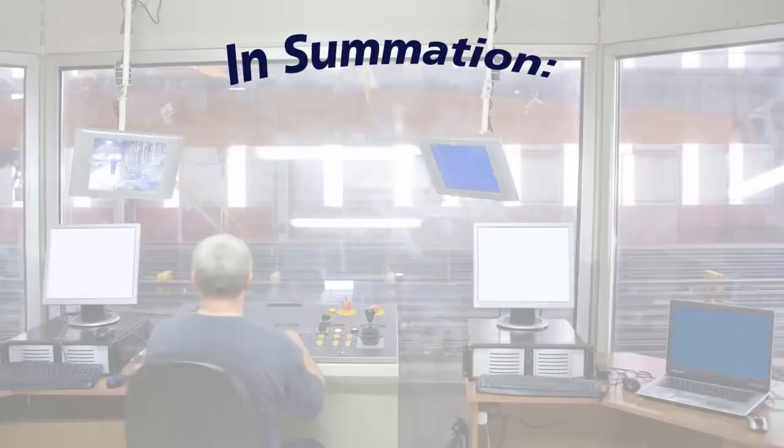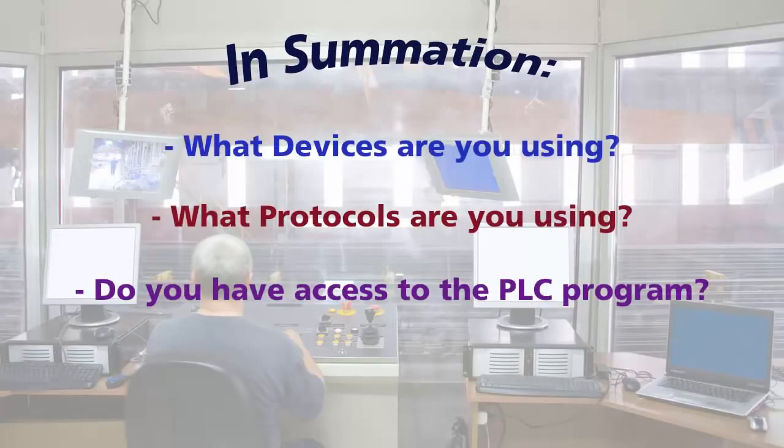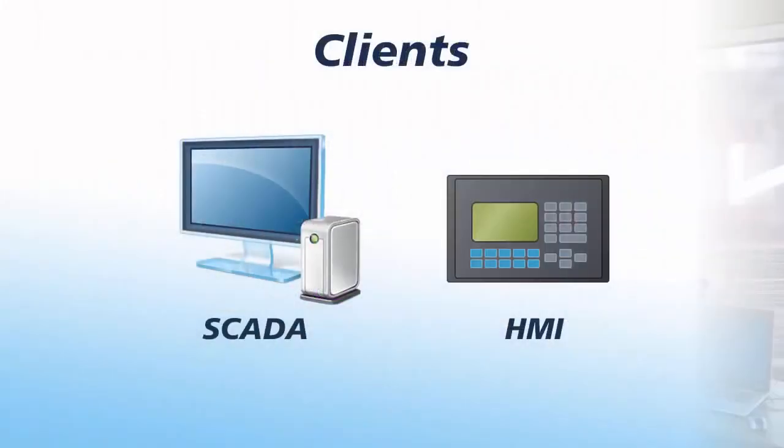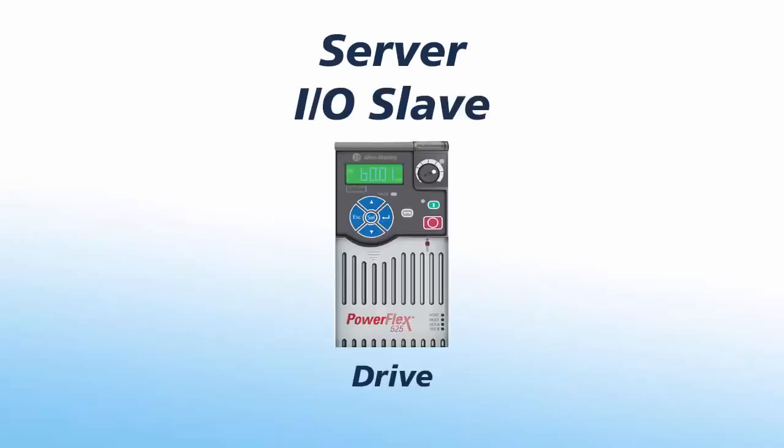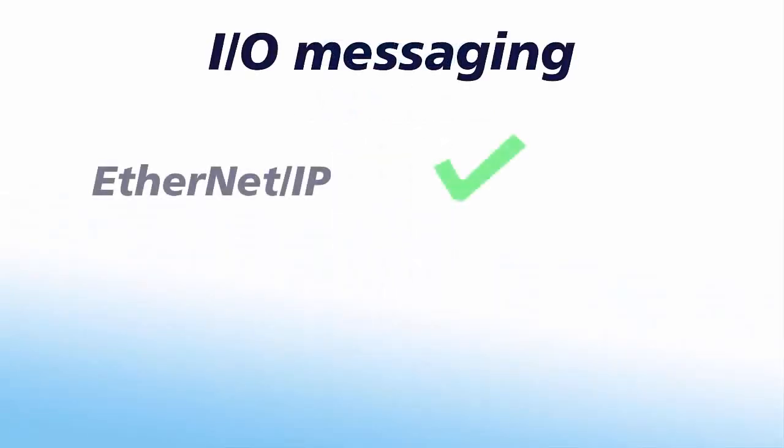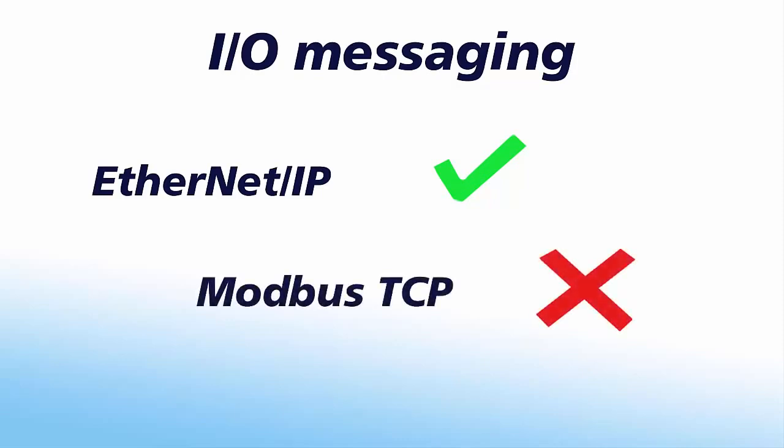So, in summation, when deciding what communication method you want to use, there are a few things you should consider. You should be mindful of what devices you're using, what protocols you're using, and whether or not you have access to the PLC program. The devices you have will determine what methods you can use. Remember, some devices can only be configured as a client or as a server. Also, not all Ethernet-based protocols can support I/O messaging. They will need to use client-server communications.